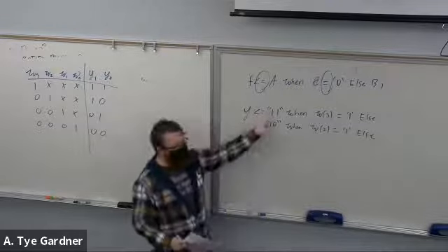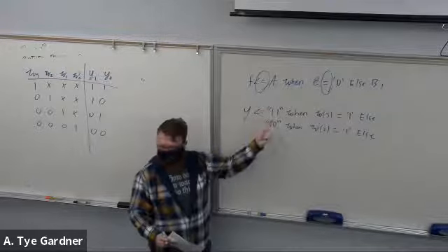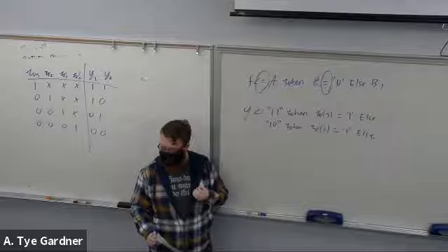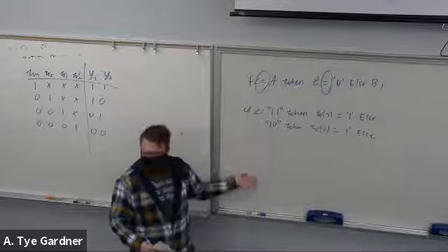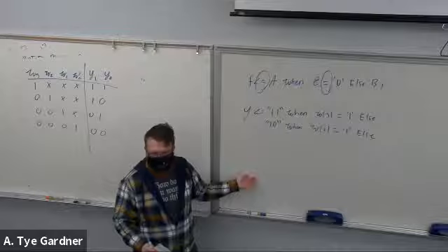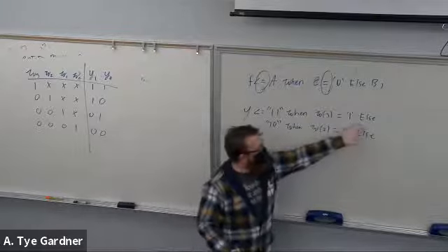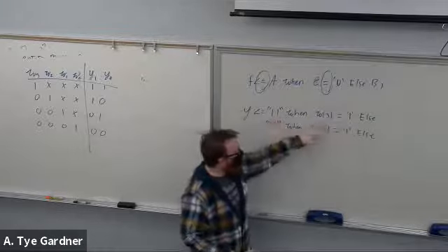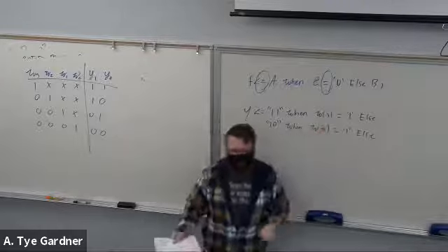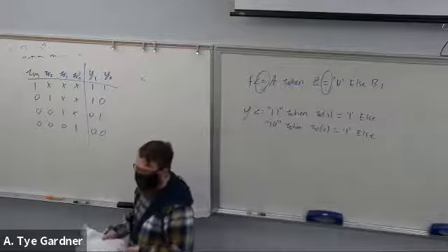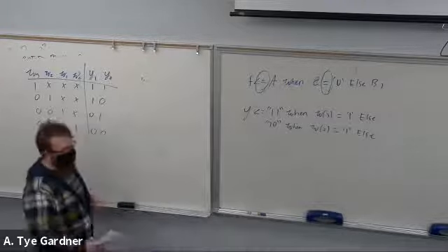Notice the quotes instead of the apostrophe because it's a vector instead of just a single bit. And now it doesn't pay any attention to the rest of this assignment statement because of this else. This says if this isn't true, do something else. But if this is true, we stop. So that's the priority encoder.